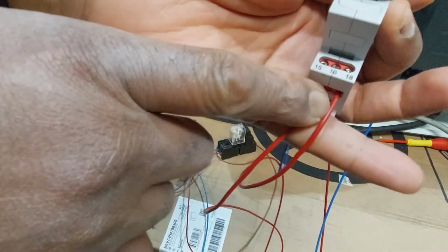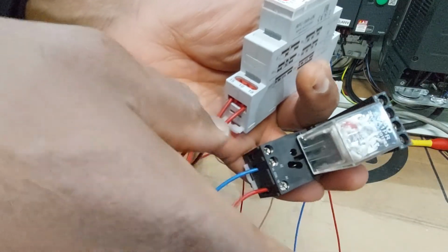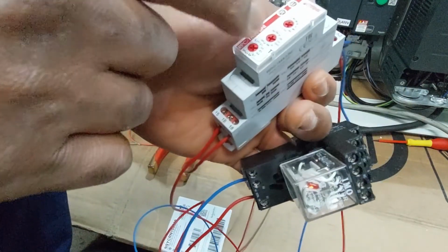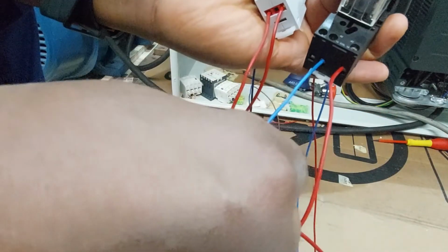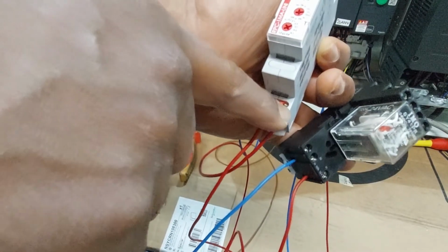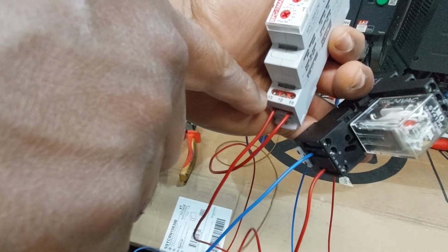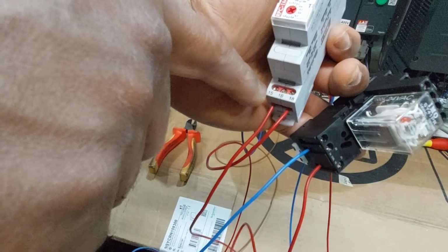The project that is going to be controlled, let's say for example, it is going to activate this relay when the time that you set has been reached. So what you do is that you supply this coil with negative, but you make the phase, you apply with neutral. All that the timer can do is to switch the contact. So it switches between 16 and 18, and then it's common.